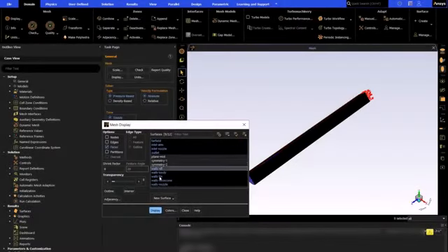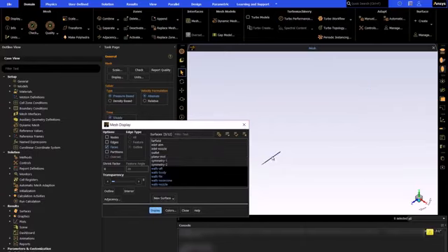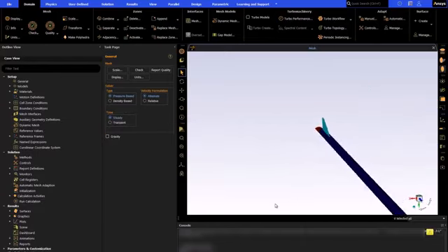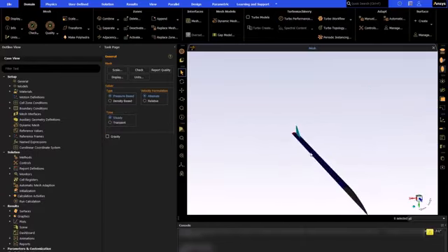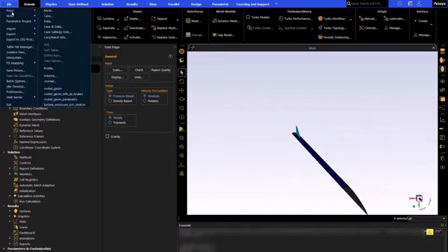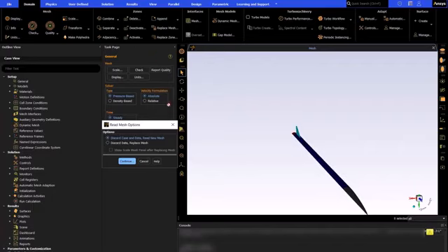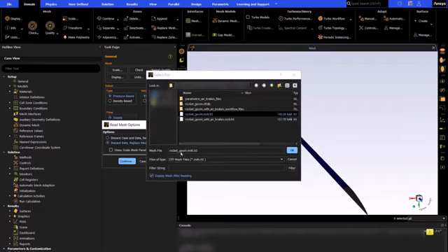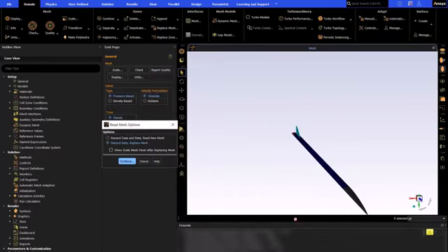And finally, we'll briefly look at how to use the same simulation case setup for different geometries. Here, I've reloaded the original base simulation case. We've exited the parametric project, as different geometries cannot be included in a single parametric study. However, if you want to reuse an existing case setup with a new meshed geometry, use File, Read, Mesh, and select Discard Data, Replace Mesh in order to keep the simulation settings, but use a new mesh.